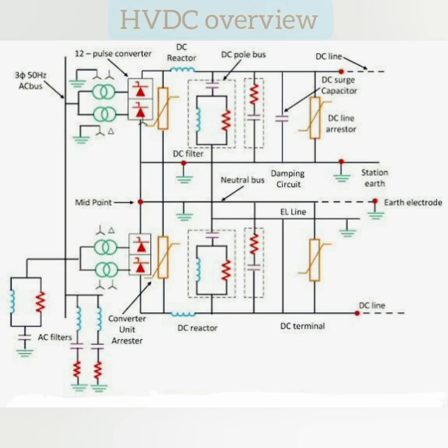Coming back to the overview of your HVDC station, this is how it works. Here we use the bipole structure, which comprises your monopole level also. The AC line or AC bus connects with your converter transformer, star-star and star-delta, which further supplies the AC supply to your 12 pulse converter. Now I am considering a single monopole level; that will be ditto for your other monopole. After it is connected to your 12 pulse converter, the thyristors get triggered and DC supply is produced by converting AC to DC.